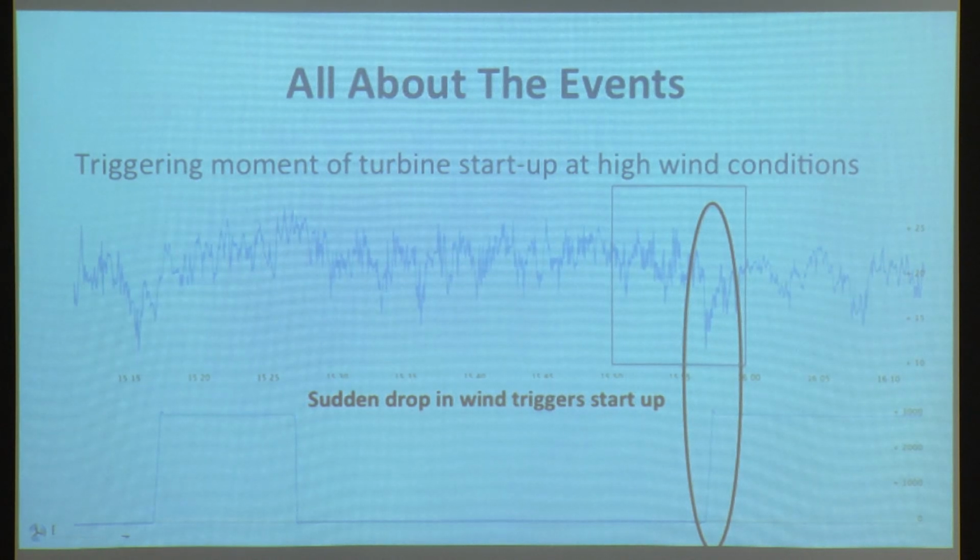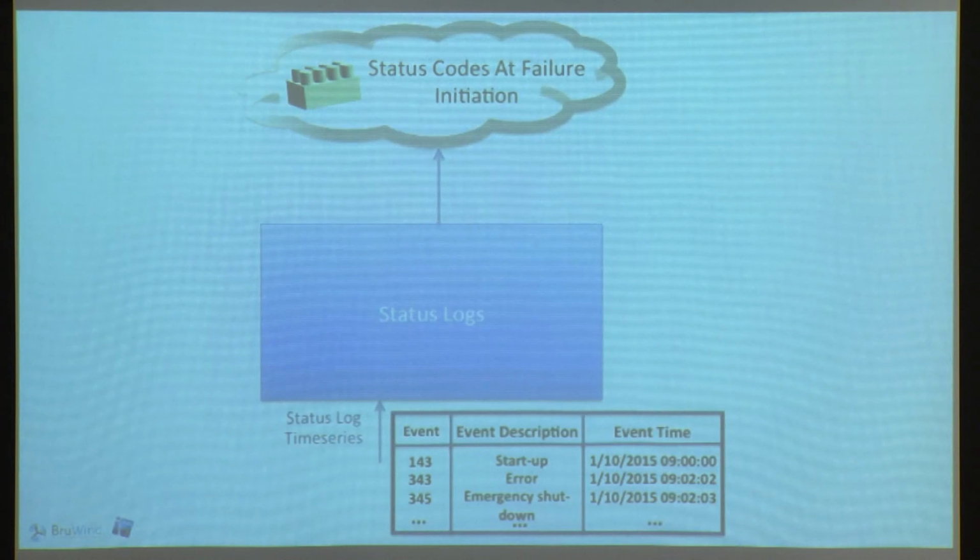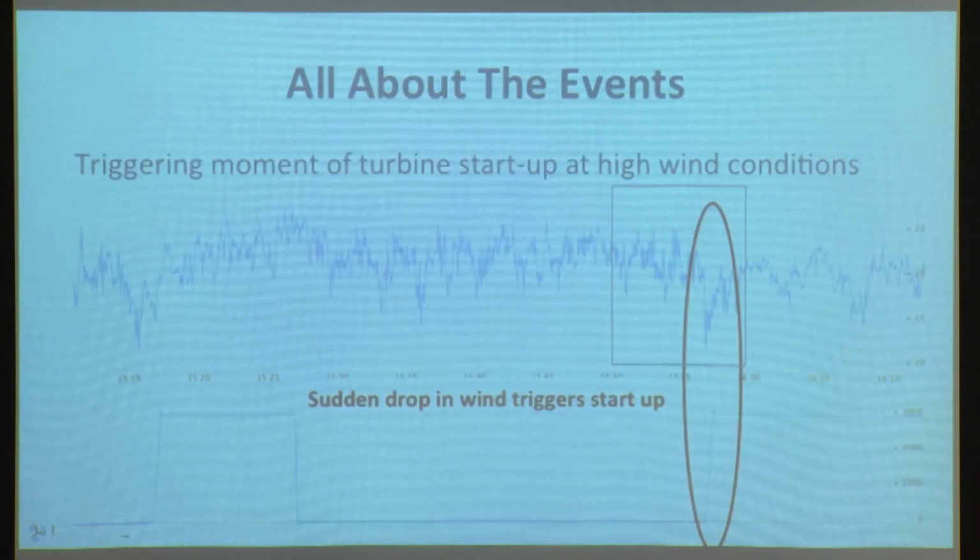It's very demanding on the electricity grid because you go from 0 to 3 megawatt and back to 0 in a short period of time. So it means that in the back there needs to be a gas central or something else that covers for this, so that you don't get fluctuation that is too high in the electricity grid. So it's something you actually don't really want. So what we are working on is really trying to detect these events, putting them in the load history, and compare turbines to each other, which one has seen more events than the other one, and is this linked to its maintenance history? So do you see more failure for these turbines or not?